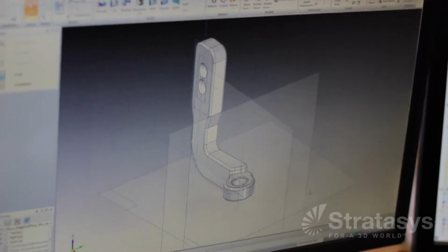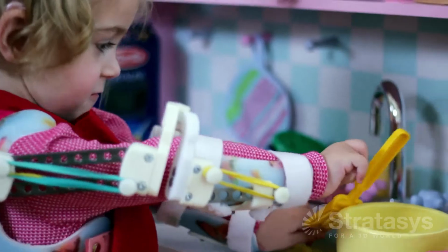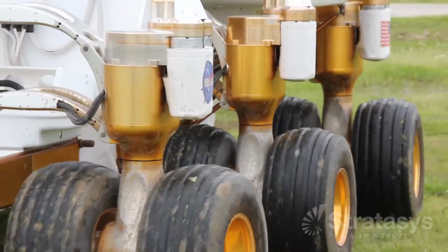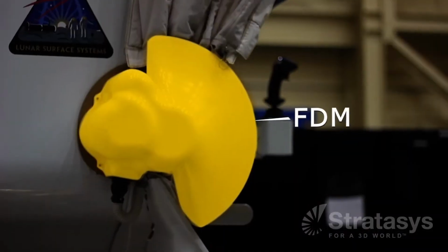So what qualifies a part as a good candidate for FDM end use? 1. The design is expected to change frequently. 2. The part is a one-off. Look for the customized product or the solutions-based products that are encountered in motorsports and processing equipment, for example.